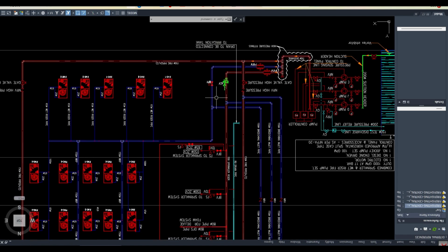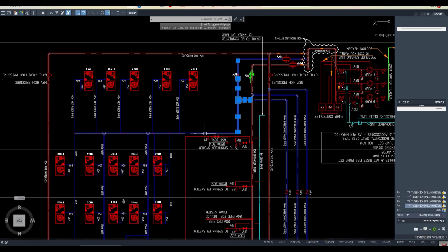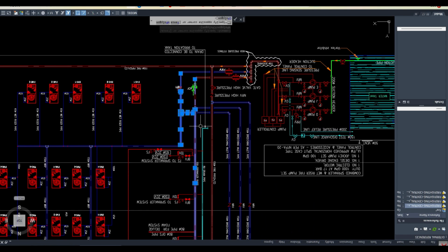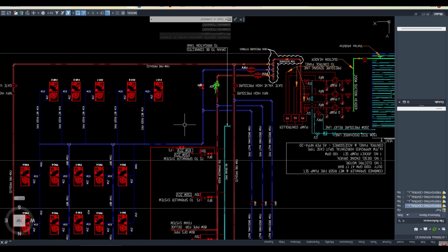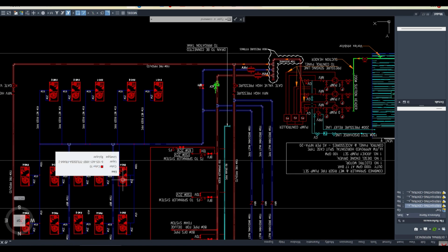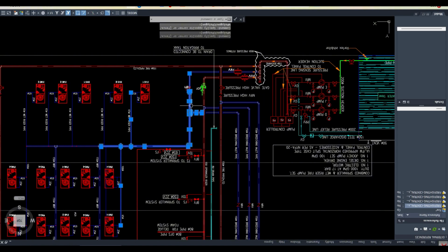So this system is the wet riser system, the blue line you can see here, right? And this red line is the sprinkler system. Sprinkler is an automatic system, and the blue line, which is the wet riser system, is a manual system. Manual means the water is automatically filled here, but the operation has to be done manually. The person has to be there to fight the fire. Now we are discussing class 1, 2 and 3, which are only about the wet riser system, this blue line system.